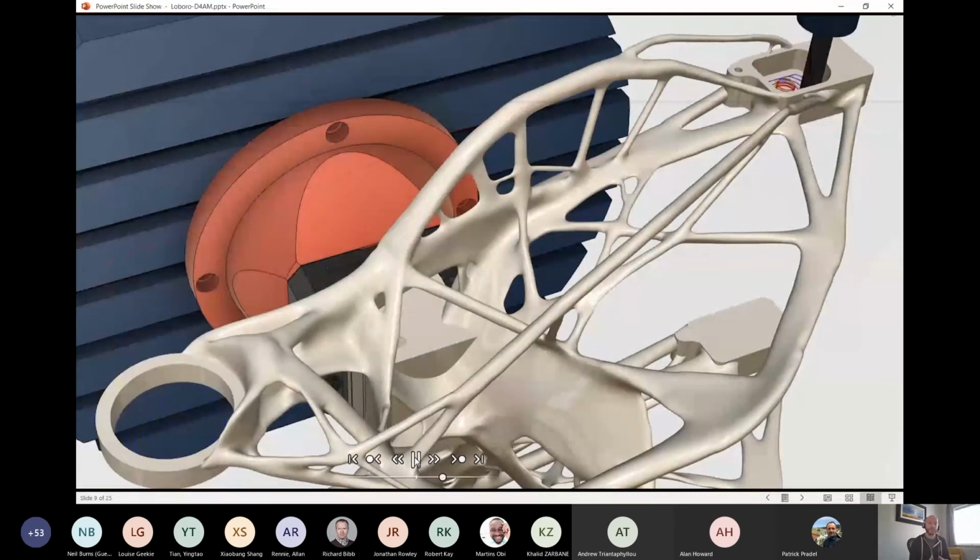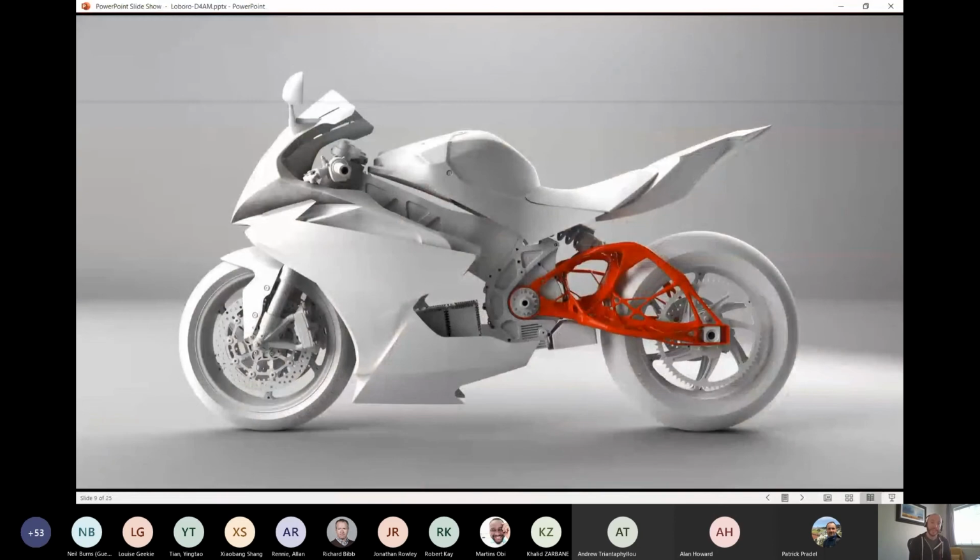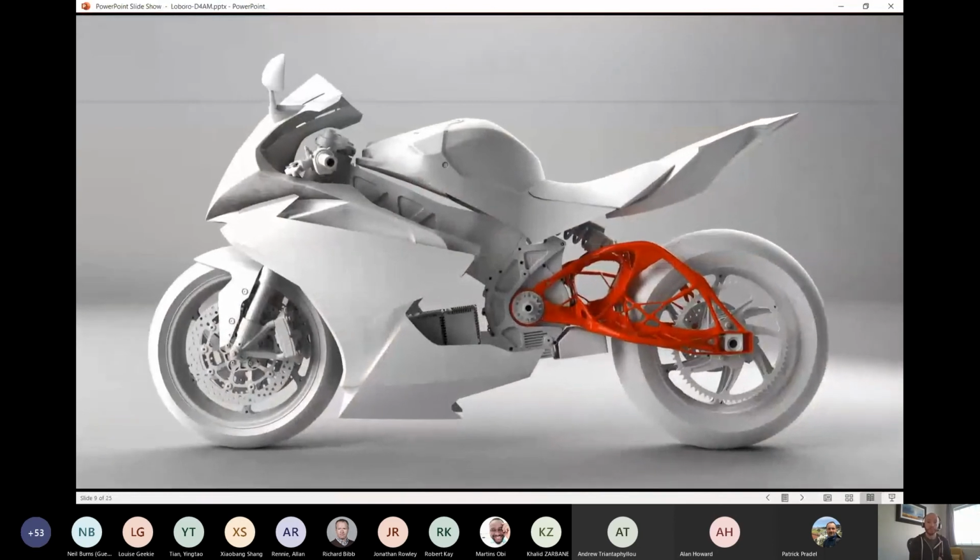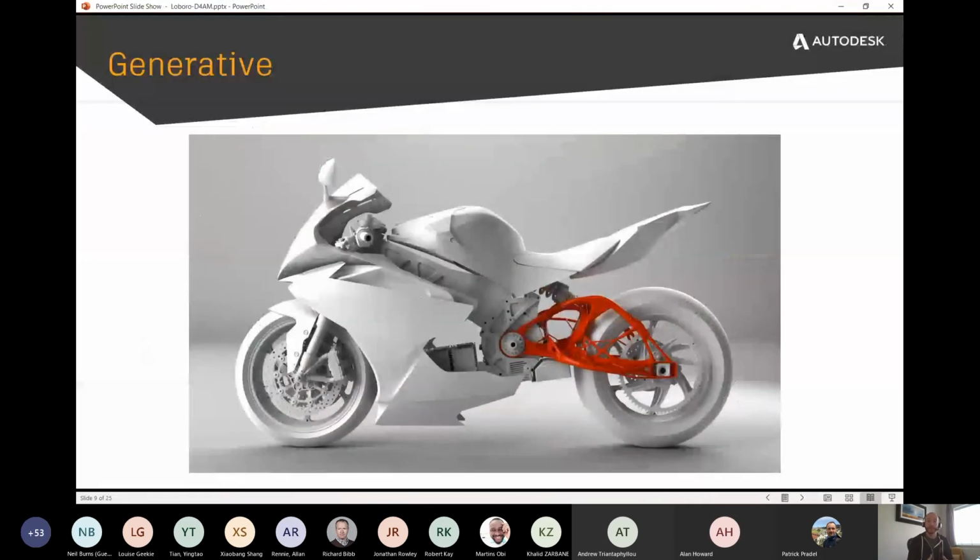So for example, if you want to create a hole in something, is the best way to create that hole a subsequent operation, i.e. machining or drilling, or is it to print that hole? Now, largely, if you want an accurate hole, then printing it is going to be quite a bad idea. You almost definitely want to machine that afterwards. And depending on how accurate the hole needs to be, you consider whether that's going to be drilled or bored, or you have various options available to you.